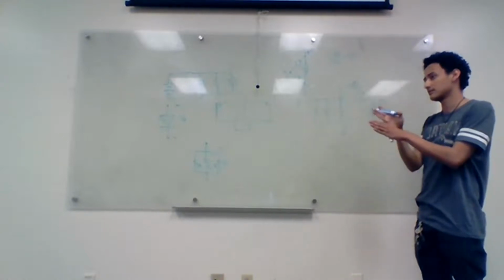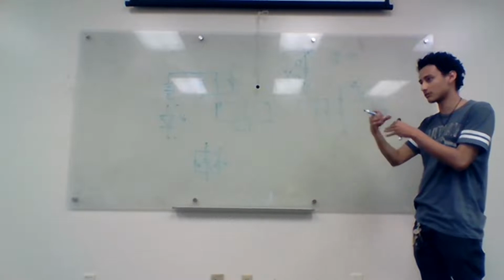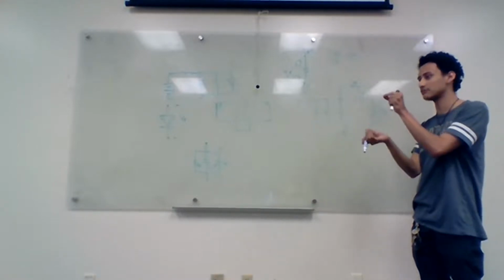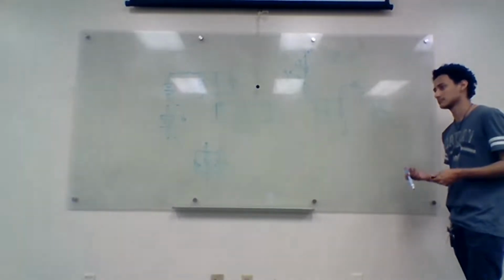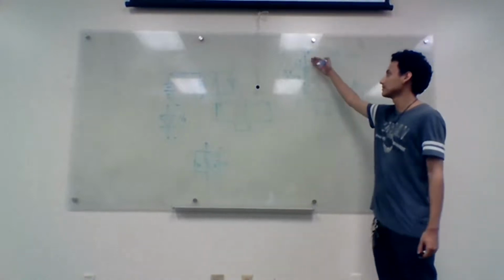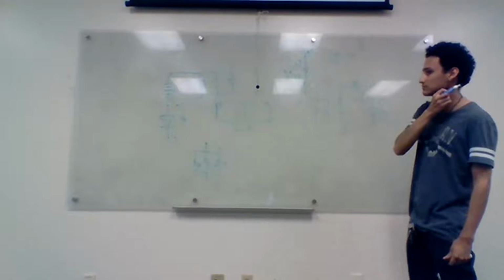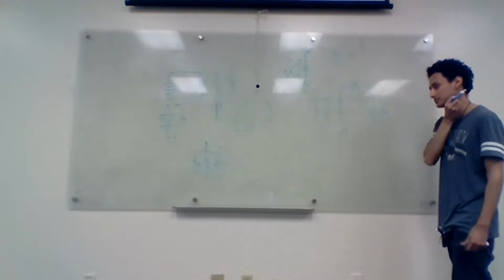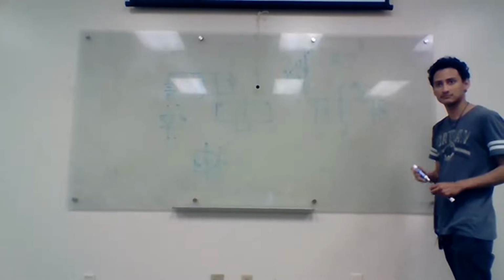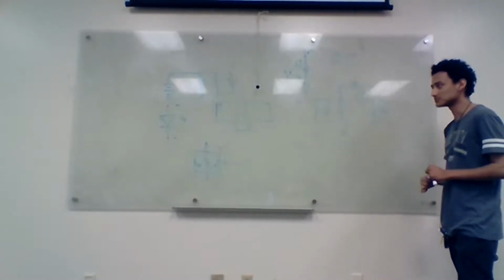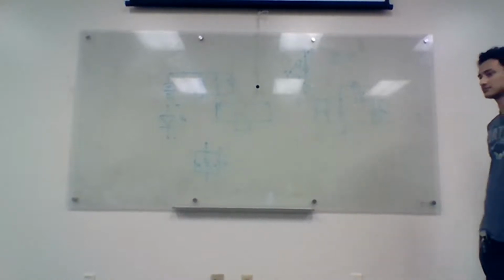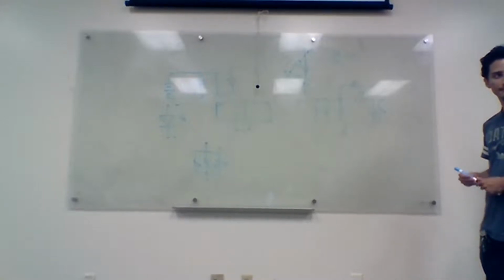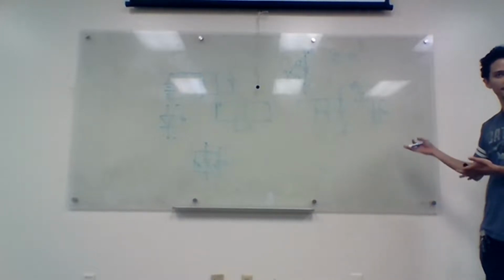If you want to look at your resistance looking into a circuit or at the output of a circuit, you take that input voltage divided by the input current, that's your input resistance. The output resistance R0 is the collector emitter voltage and current relationship. So conceptually, that's where this exam is, or should be. Do you guys have any questions on this?